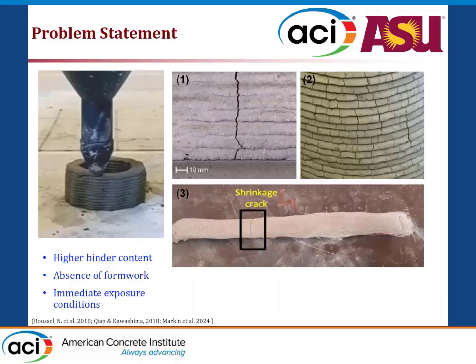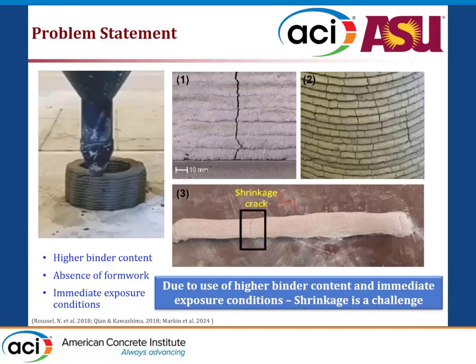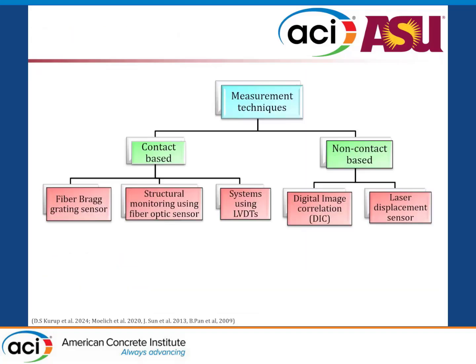Again, based on how much surface area you expose, cracking chances can go higher. In a typical industrial application, maybe the binder contents are slightly lower, but in our case, when we work in a lab, we usually have higher binder content, resulting in more autogenous shrinkage too.